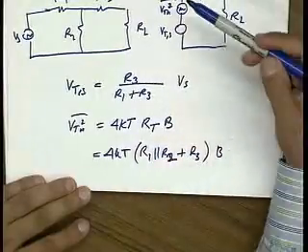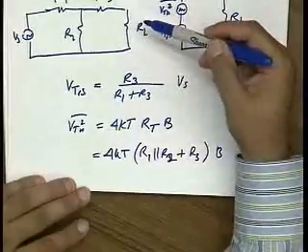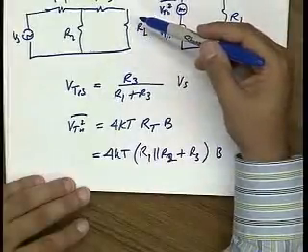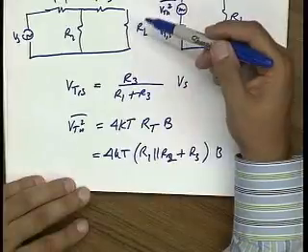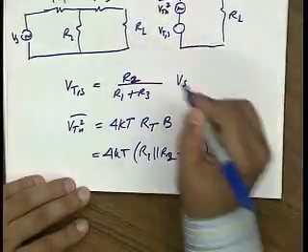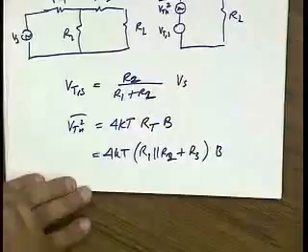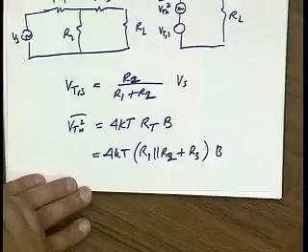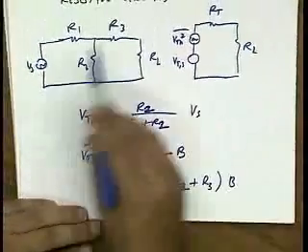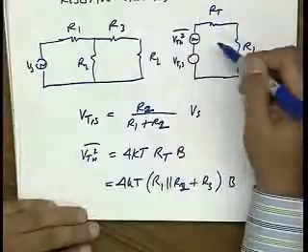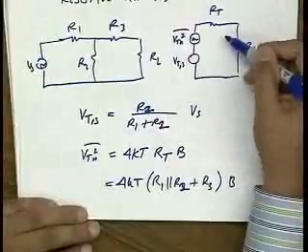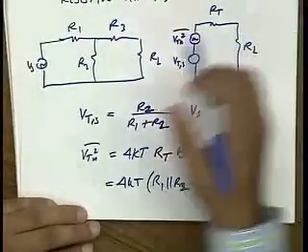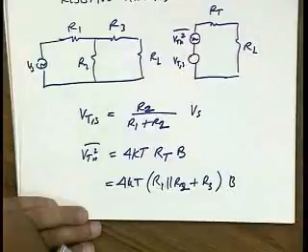Okay, is this right? My notes might be wrong here. So open circuit voltage should be R2 over R1 plus R2. Okay? So you can use circuit theory to simplify your circuits, and for the final resistance value you have, you just make sure you associate noise with that resistor, and you get the right answer. Okay? Questions?